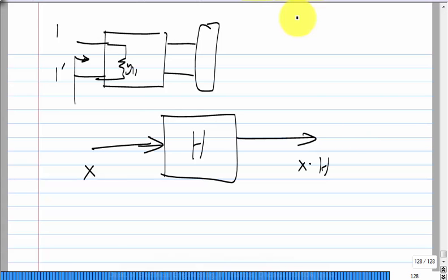Any questions about this idea of unilateral nature of 2 ports? Unilateral, as the name suggests, means that the control is flowing only in one direction. So either Y12 should be 0 or Y21 must be 0. And it of course means that if any of the 1, 2 parameters is 0, all the others will also be 0. Any questions?